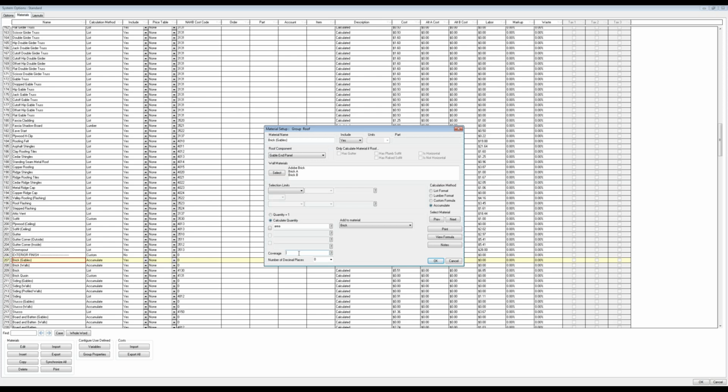We're going to add the coverage here. As I said, one square foot is going to be accounted for by 6 bricks. So 1 brick then covers 0.1666 square feet. So that's how much square footage 1 brick covers. So again, when we're changing units, we simply say how much does 1 unit cover. The base unit of SoftList, all values are determined in feet or square feet or cubic feet, depending on if it's a volume, area, or just a length.